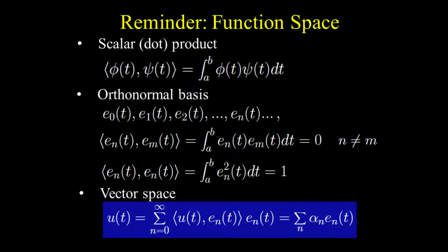We can also introduce the concept of the orthonormal basis in this space of signals based on the definition of scalar product. The condition that the scalar product is 0 says that every pair of signals of the system is orthogonal, whereas the condition that the scalar product of each function is 1 says that each signal is normalized.